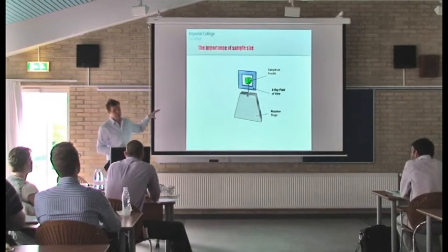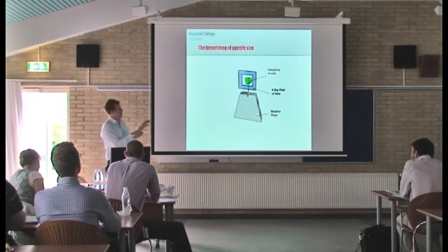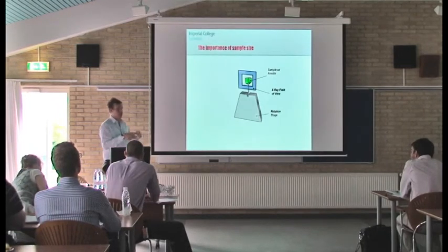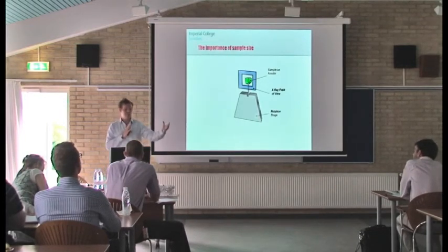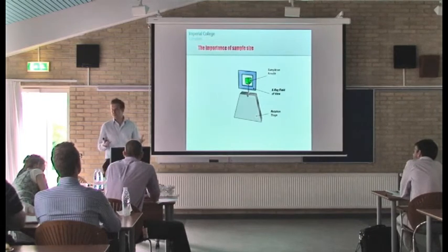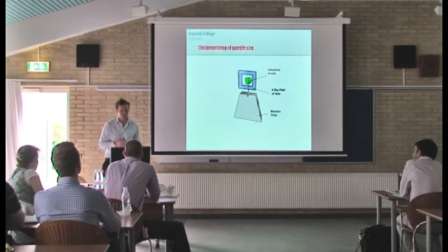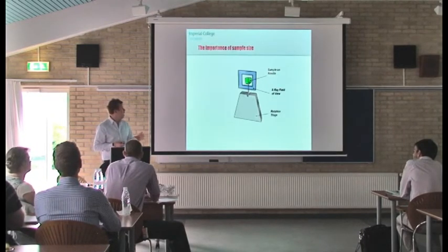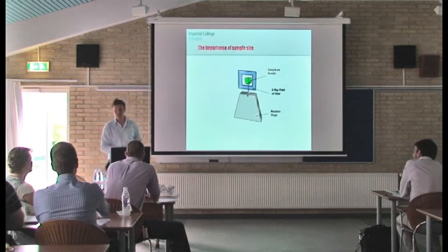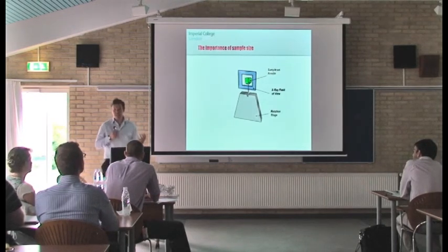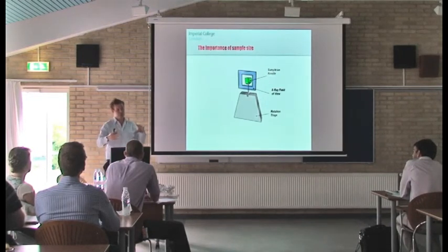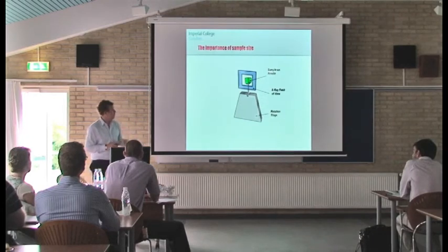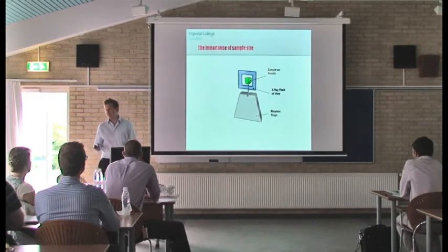But because we're looking at fields of view of between 15 and 65 microns, we need to maintain the sample within that field of view in order to maintain the integrity of our data and also to optimize the reconstruction algorithm. Now, if we drift in and out of the field of view, you end up with an incomplete data set. This is perhaps comparable to TEM tomography, some of you may be familiar with. You get this missing wedge type problem. And if you have a missing wedge, it introduces noise into your reconstruction, and it makes it difficult to get any phase analysis because you're no longer sure where your contribution from sample geometry and your contribution from sample phase has come from. So getting the right sample geometry is actually very important, but obviously with a field of view of like 15 microns,